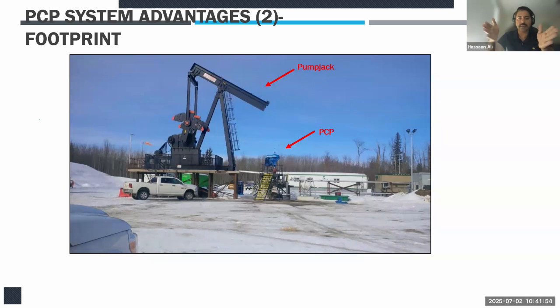The pump geometry and the elastomer used in the US, well, not even the US, let's talk about a particular field. If one field is using a certain elastomer and pump, you go to the next field and you may have to change your elastomer. The reason is that fluid properties differ between fields. Some fields have high H2S, some do not. Some have high water cut, some have almost zero water cut. So your pump selection will change. It's specific to a field, not to an area.